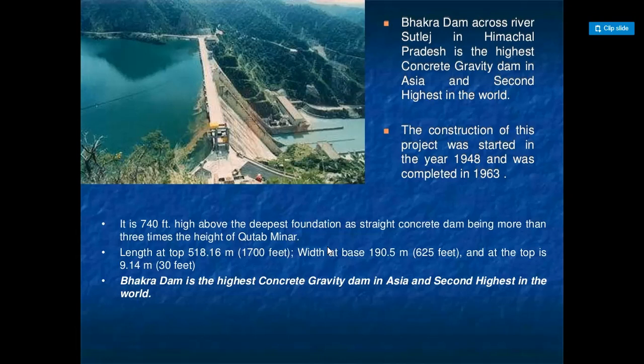Forces acting on a gravity dam. A gravity dam is subjected to the following main forces. Water pressure, H1; earth and silt pressure, H2, due to deposition of silt; reservoir behavior, H3, where wind and other natural causes induce movement in the reservoir as waves; ice loading, H4, and tailwater, H5, due to water pounding downstream from the dam; seismic force, H6, which is the force acting on the dam in the horizontal plane.